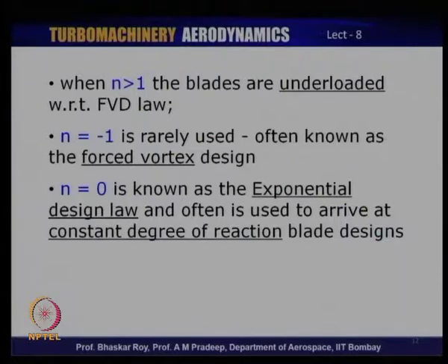If you are underloading, the flow across the tip would be of a lower strength, and hence the tip flow vortex will be of a lower strength, and hence the blade will hopefully be of a higher efficiency and hopefully of better stall characteristics. So, these are the thoughts that are put together in using values of n less than 1 and more than 1.